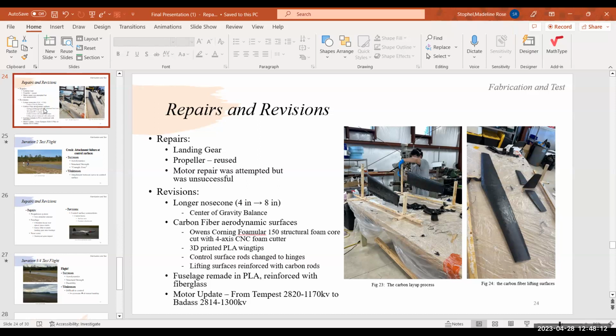You're flying at such a close range that it's not a huge issue. And Group 1 also wrapped their fuselage in carbon fiber, and it's fine. In a general sense, that should be a design consideration if you're flying long range and really far away, but for such a short plane, you can wrap it no problem. Fiberglass is heavier, but it's also cheaper, and for the stiffness requirement that you need, it probably works just as fine.